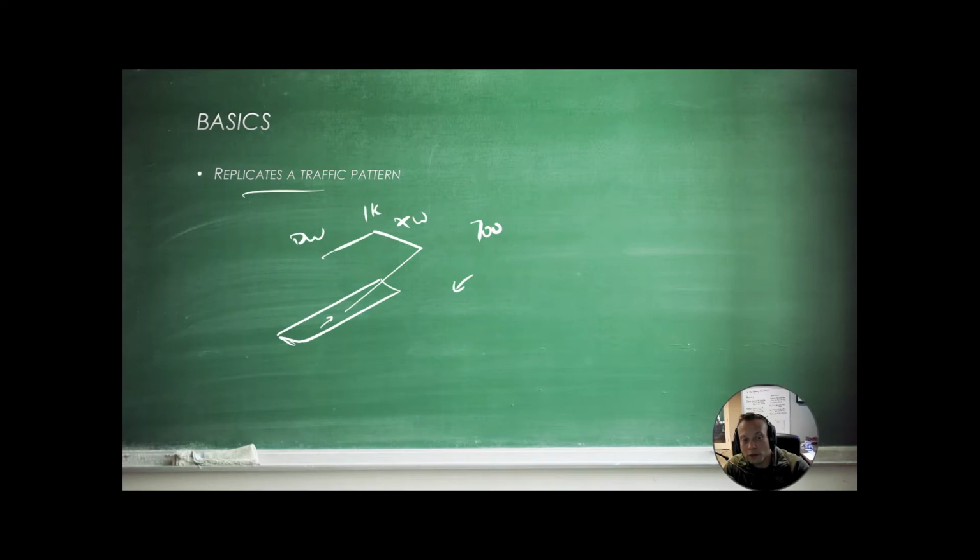And as we turn downwind, we're going to fly parallel to the runway and maintain 1,000 feet above the surface until we are abeam the numbers. Let's say this is 1-6. We're going to keep flying until we're abeam the numbers, basically level with our landing surface. And we're going to start messing with our power settings and execute a 500 foot per minute rate of descent and descend down to, again, 700 feet above the ground, turn base, and then turn final.